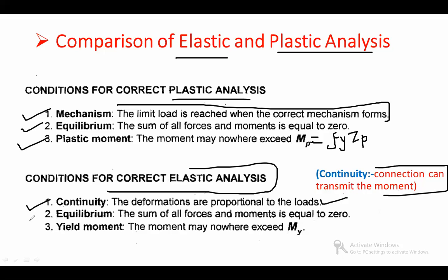Then second is equilibrium condition: sum of all the forces and moments is equal to 0. And third condition in case of elastic analysis is My is equal to Fy into elastic section modulus Ze. Right? So remember, these are the 3 conditions of plastic analysis and 3 conditions of elastic analysis.